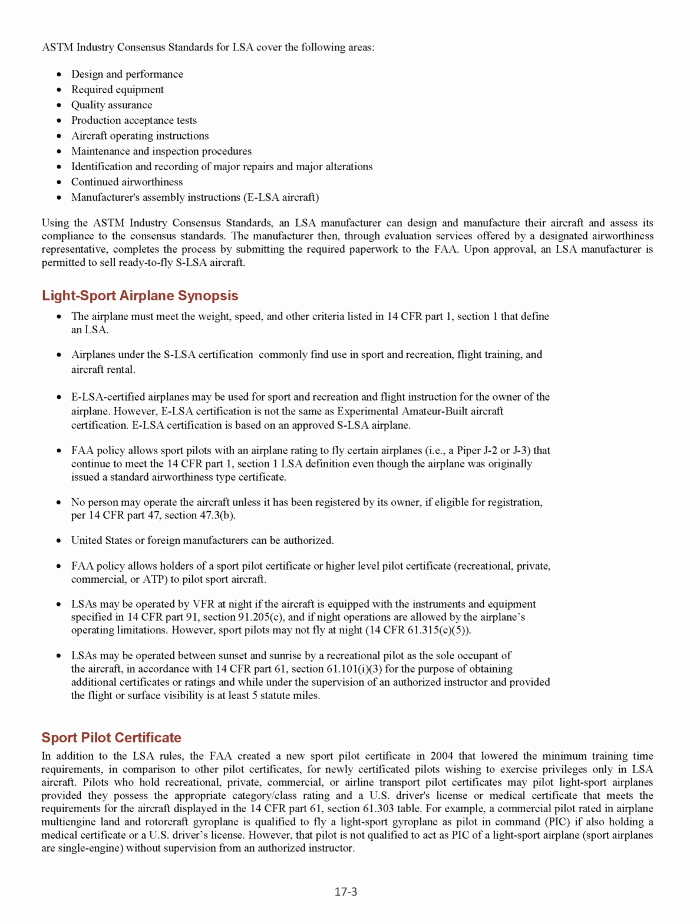LSAs may be operated between sunset and sunrise by a recreational pilot as the sole occupant of the aircraft, in accordance with 14 CFR Part 61, Section 61.101(i)(3), for the purpose of obtaining additional certificates or ratings and while under the supervision of an authorized instructor and provided the flight or surface visibility is at least 5 statute miles.